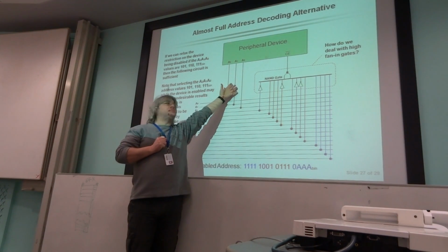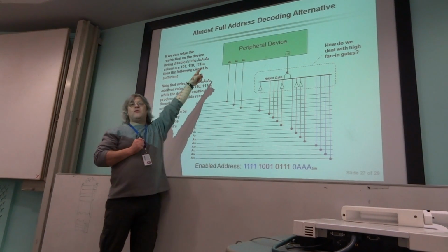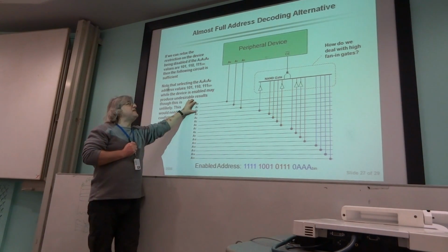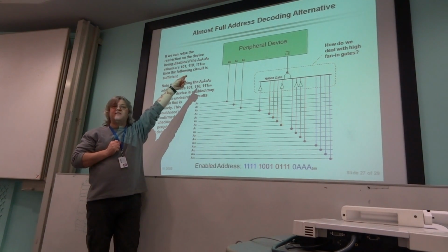The only downside of this approach really is there are 3 combinations here where this device will be awake, but those 3 values don't have any meaning in terms of accessing internal registers in that device, because it only has 5 registers, not 8.